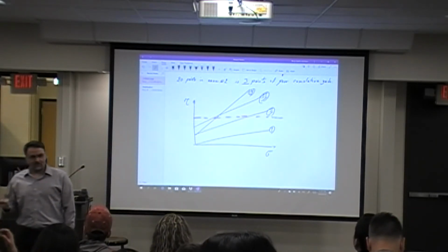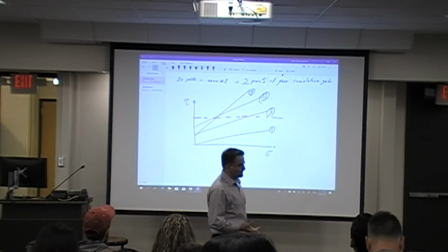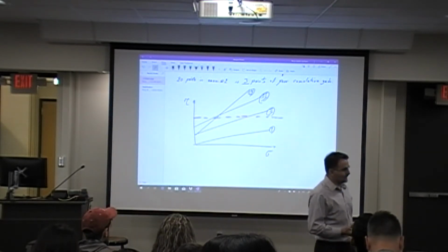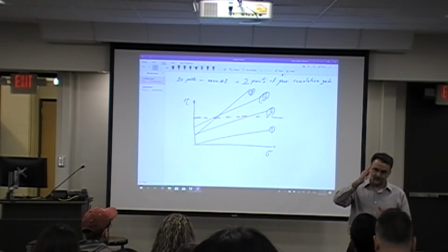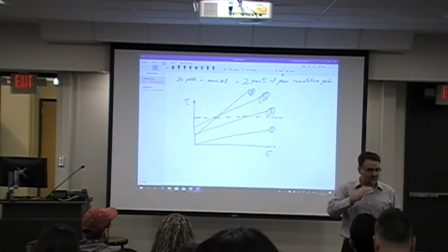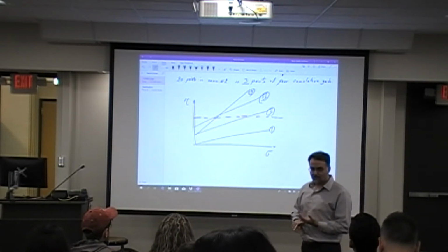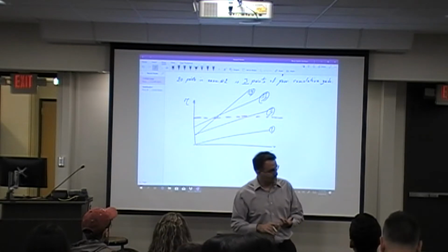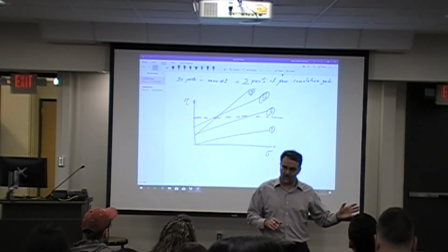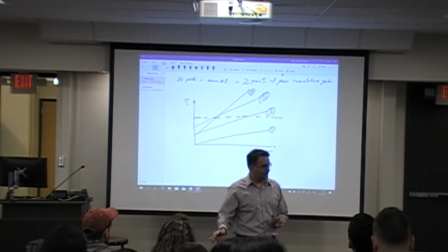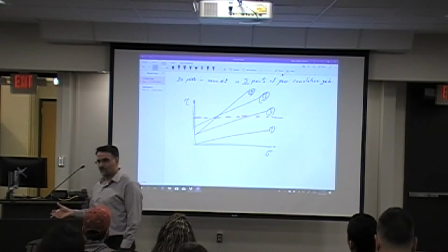Now, the last question has to do with parametric analysis of geostatic stresses. And that was, again, simple and straightforward. All you needed to do is basically plot the vertical stresses versus depth. How do you calculate that? Gamma 1 times H1, then gamma 2 times H2 plus gamma 1 H1, and all the way at the bottom of the layer would be gamma 1 H1 plus gamma 2 H2 plus gamma 3 H3.